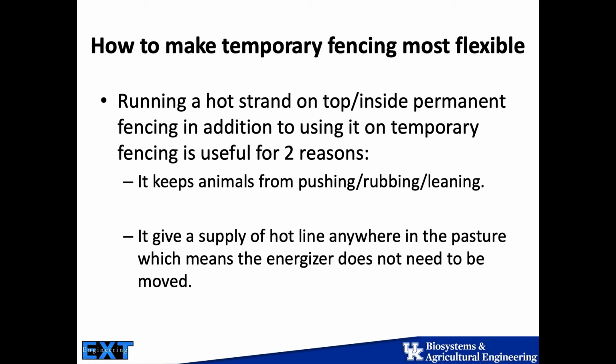Fortunately, here in Kentucky, we don't have soils that tend to be bad for grounding. We tend to have pretty good soils. We don't have high mineral soils and stuff that tend to really struggle with grounding, which is good. But it depends on the farm and the location as to how well they ground out. And the longer the poly wire, the more important that ground is, because the poly wire is only going to carry so much charge, and you have to have enough response to be able to bring that electrical current back around to get a good shock on it.